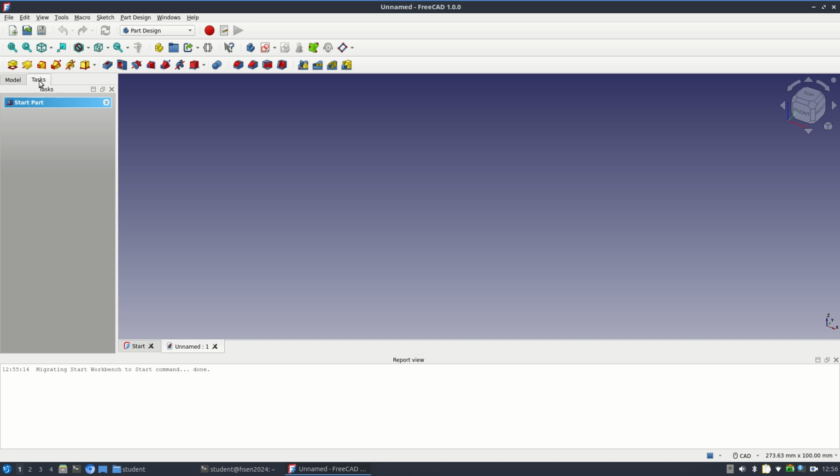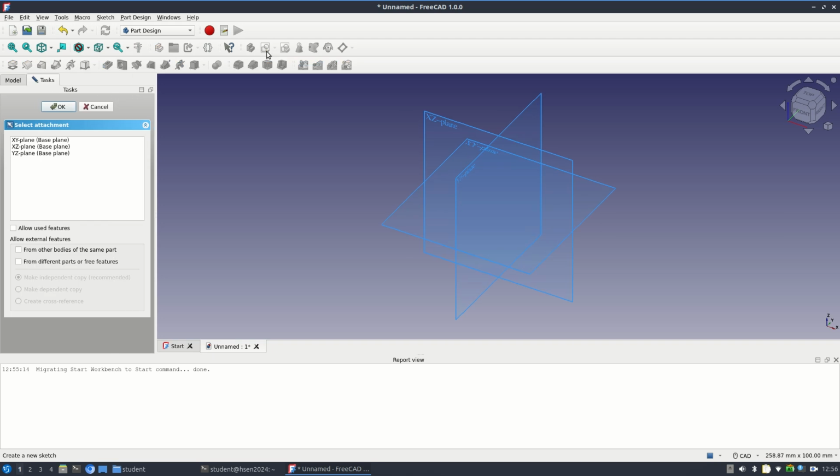All right. So the first thing that we're going to do is just create our model. So first we have to create a body, and then inside of the body, then we can start putting our sketches. See? If we just start with a sketch with no body, we're going to have problems. So we need to be sketching on the X and Y plane, right? So later on, we don't have to actually change axis for the CNC machine, and we're less prone to actually have problems. Okay.